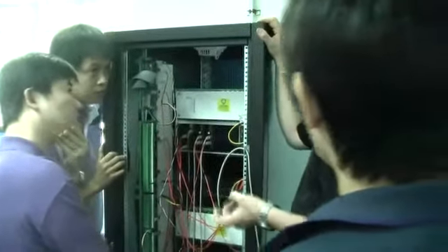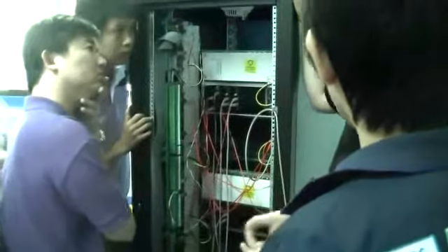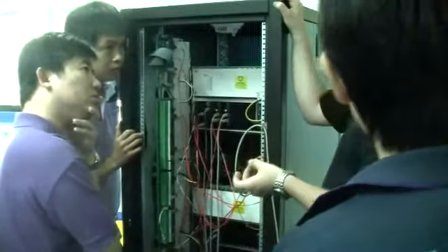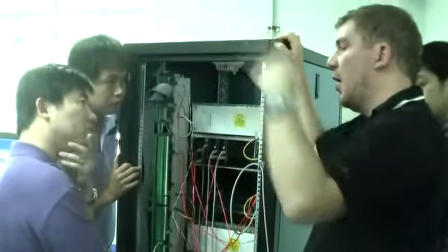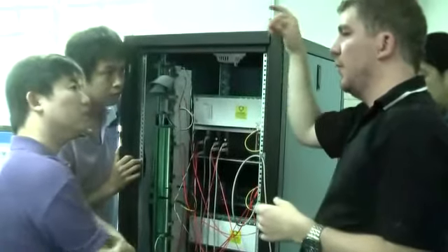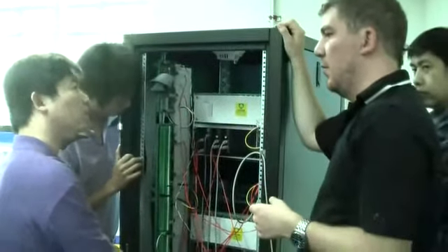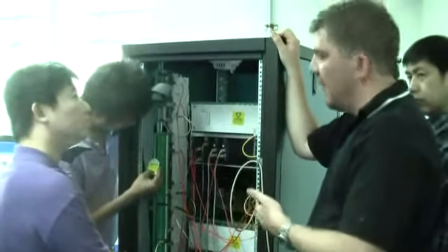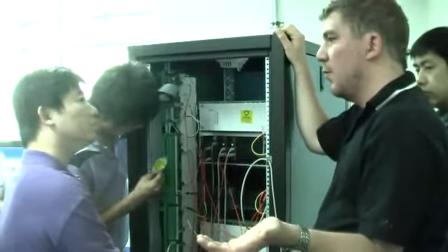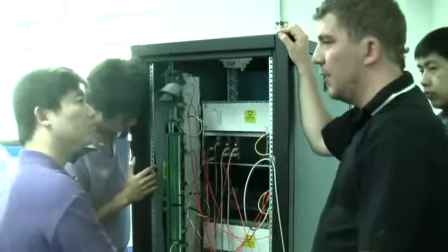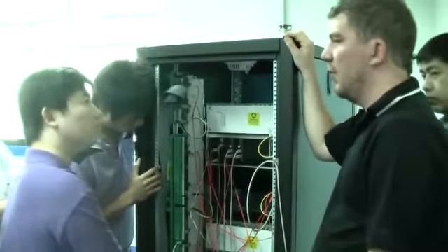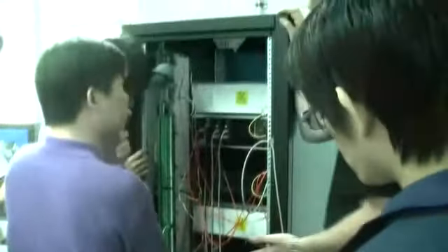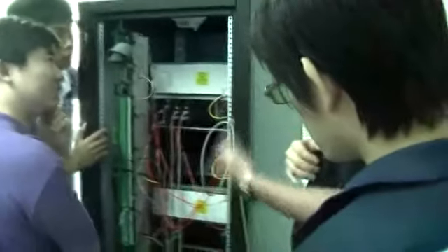The digital output is controlled by the RTDS. So in runtime, those switches, I control it. So I choose whether it's low or high. So you would send that to a controller maybe, a controller outside the RTDS, but we don't use it for relay testing because for the digital outputs, usually for a relay you need a breaker status, right?